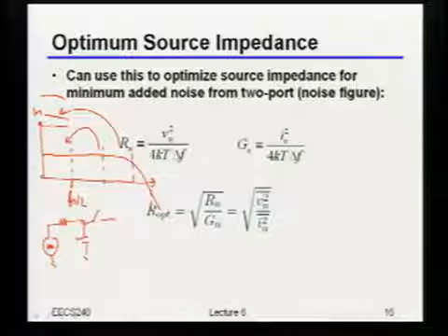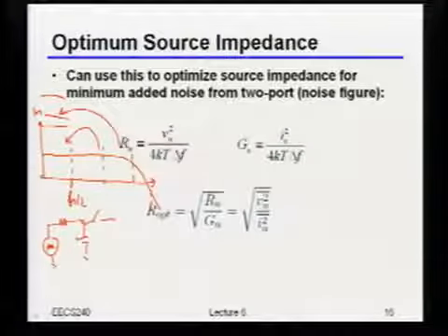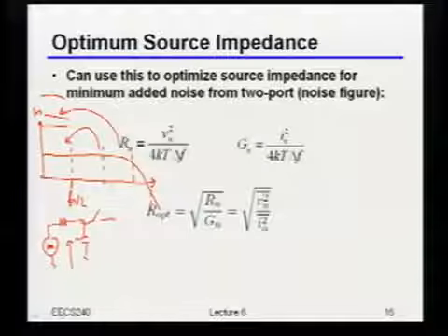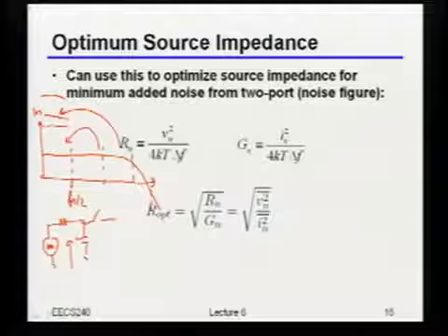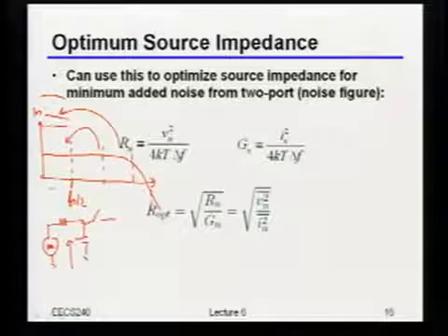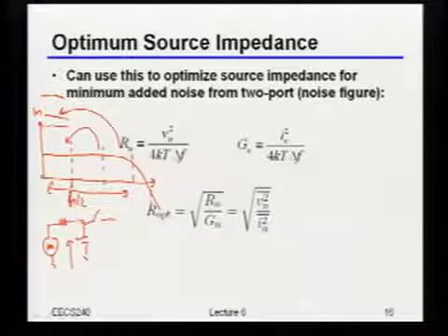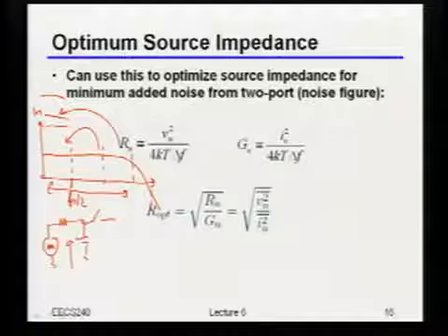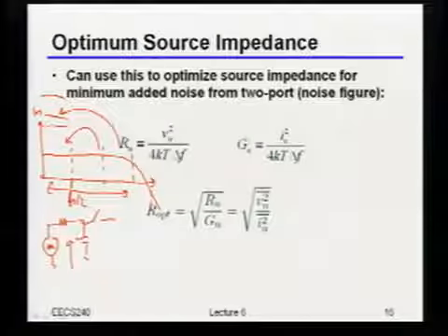So that means that if I have a really wide bandwidth in continuous time, when I look at it in the sample domain, it should still basically look white. Because I'm just taking all these chunks of white noise and folding them back on top of each other several times before I actually start filtering. Does this make sense to people?